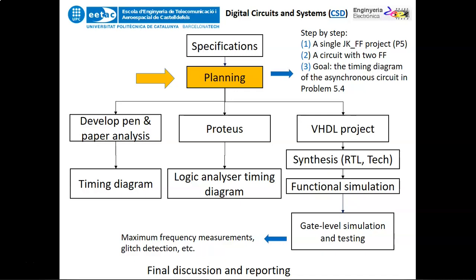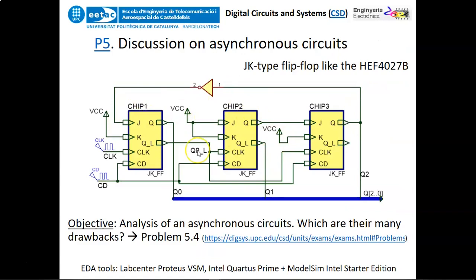And when you get some experience with this, you can reach the final goal, which is finding the timing diagram of the full picture, for example this one, problem 5.4. But you've got many more in the collection, the 5.9, the 5.8, several of them, and all of them thought up in the same way. You have on the table several flip-flops and gates, and you connect them in any way. So it's just a kind of drilling exercise to get used to signals, clear directs, ones and zeros, and clocks and the like, right?